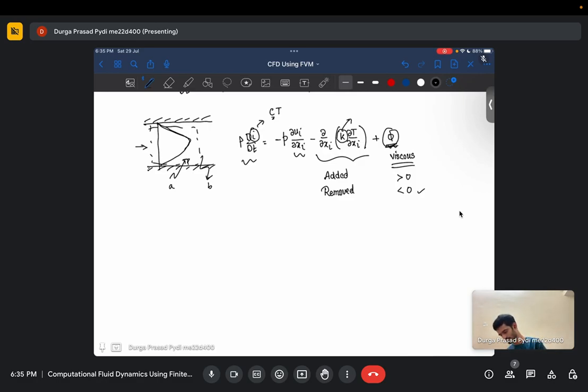This viscous term, we have discussed this, right? It is the term d by dx_i of tau_ij u_j. That's the term. This is the energy term due to shear stress, what we discussed recently. This is due to viscous effects, and this comes in your rho times dE/dt